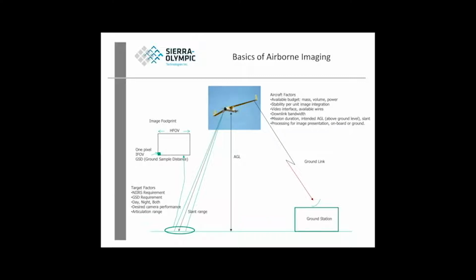And the wider your field of view, if you're doing wide field of view, your stabilization is lower because your pixels are much bigger and hopefully your vibration isn't that great. As you go narrower and narrower, the relative ratio between vibration effect and IFOV gets greater and greater, and the requirement for stabilization gets higher and higher.